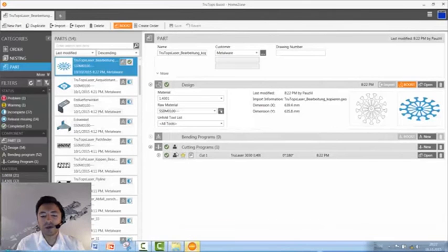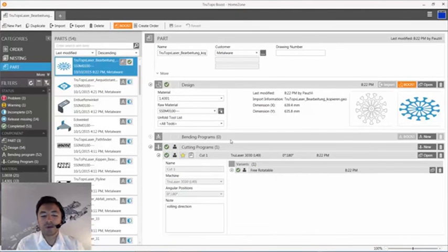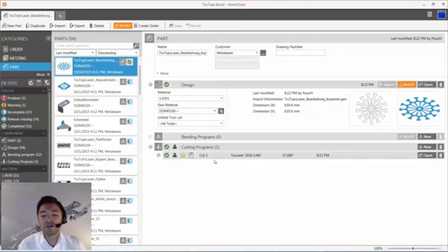So of course we don't create the NC program. What you see within the home zone, there's our notification or note. You see that it was changed manually, and that's our favorite cutting program. So you could create several cutting programs, and of course for different machines, for the punching machine and another processing, and for example for the night shift, you would create parts with micro joints, and exactly that cutting program which you specify within the nesting will be taken.